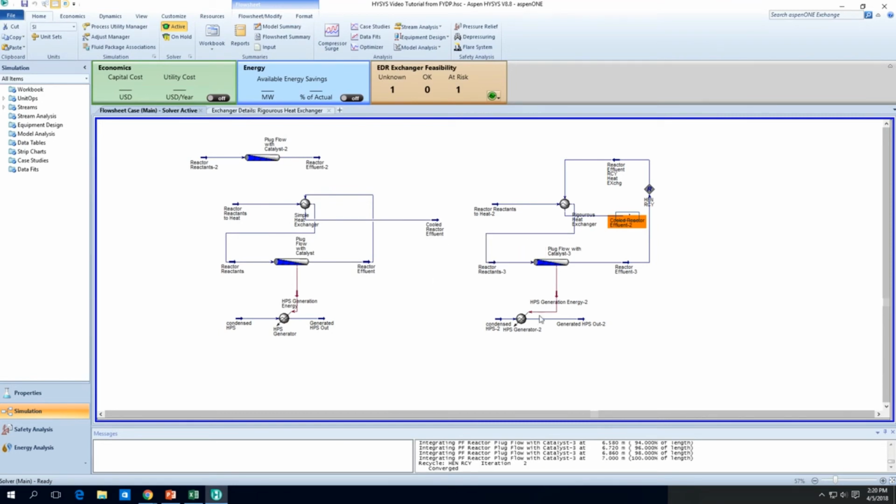So yeah, that's how you do a proper heat exchanger sizing. And yeah, that's all for now. We have gotten a good pressure drop range, a reasonable pressure drop of about 100 kilopascal across the whole thing, across this plug flow reactor and this heat exchanger. And of course, if you want to include pipes, you can, but maybe in the next video I should show you more about pipes and all that kind of stuff.